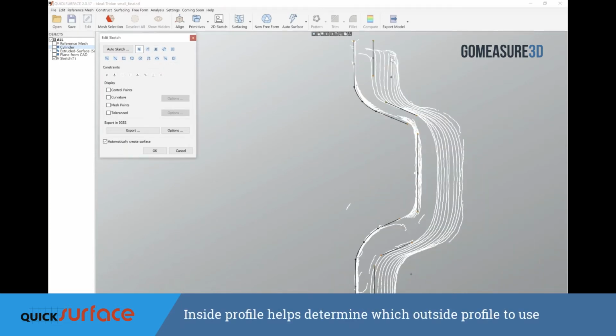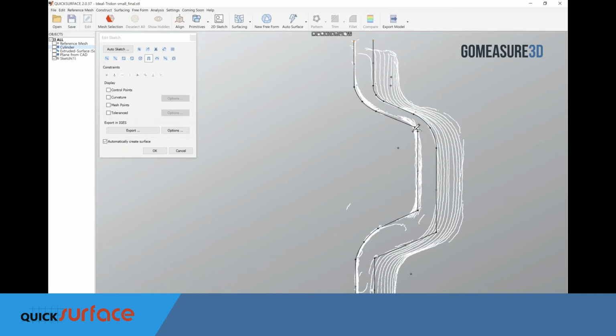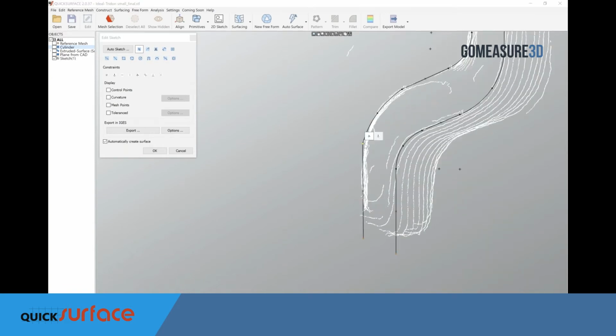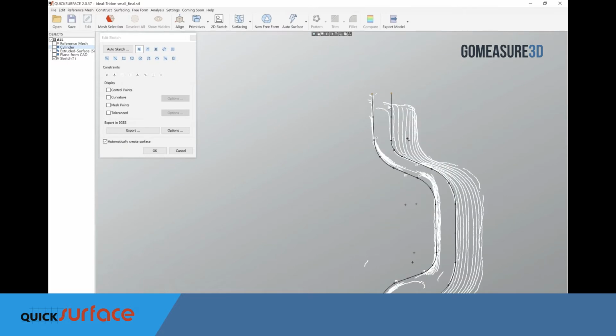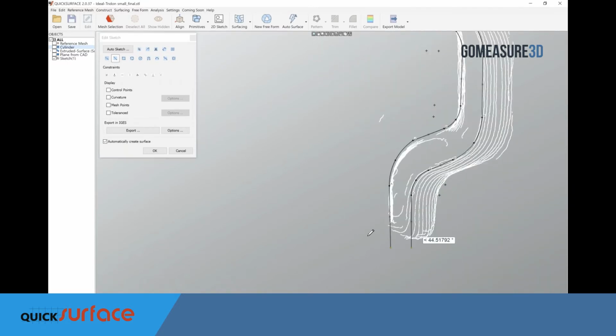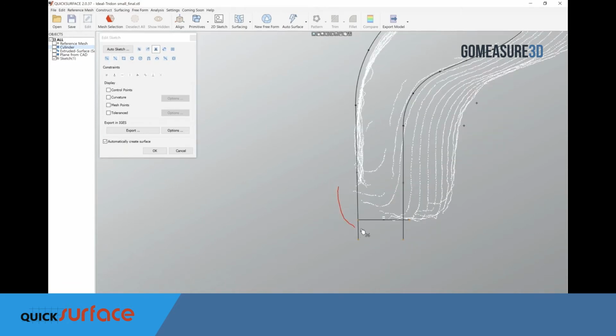So we're going to use that inside surface as our driving surface for our part, and then for the outside surface, we're going to use the innermost portion, as we can most likely determine from this part that the outside surface is going to be one particular thickness that's thinner than the rest of the part, or when the object was scanned, the misalignment caused it to become thicker than it truly was. So we'll sketch this out. We'll get our sketch trued in to where we feel like it's appropriate.